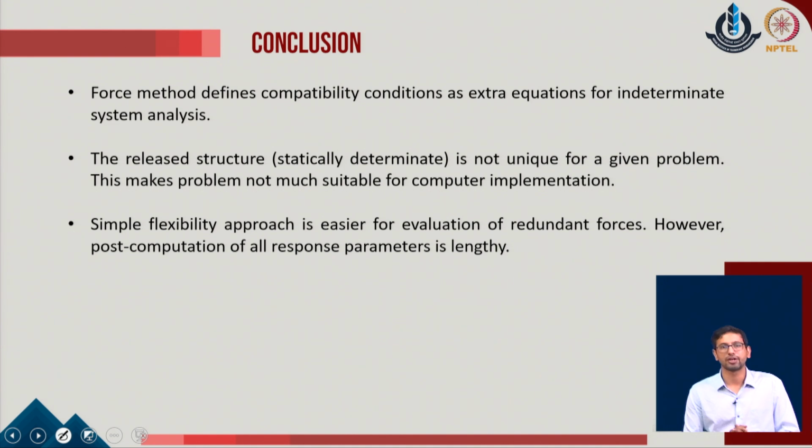And then finally, we understood that the simple flexibility approach is easier to evaluate the redundant forces, but the post processing or the post computation of the remaining analysis results become relatively difficult. And with this, we now look forward to look for a second method of the indeterminate system analysis, which is called as the displacement method, and we will look it from the perspective of the stiffness approach.